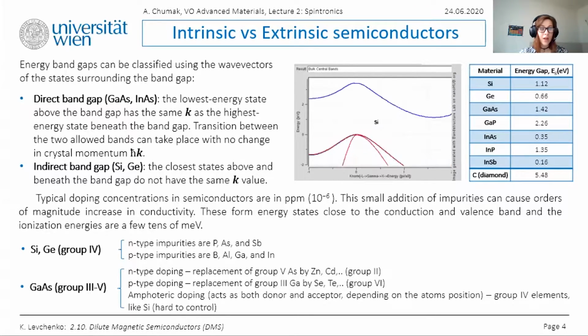In the opposite case, for the P-type materials, we are popping in a trivalent element, so it has 3 electrons in its valence shell, and it shares these 3 electrons with 3 neighboring silicon atoms, with the 4th silicon atom left unpaired. We are having a hole, a void in the lattice, and this deficiency creates the P-type material.